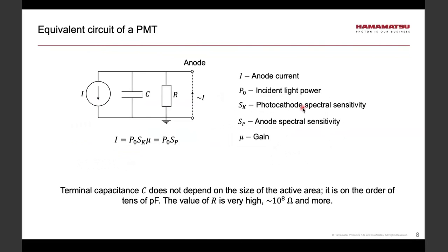It is very convenient to represent operation of any photodetector using equivalent electrical circuit. And so what you see on left-hand side is such circuit for a PMT.